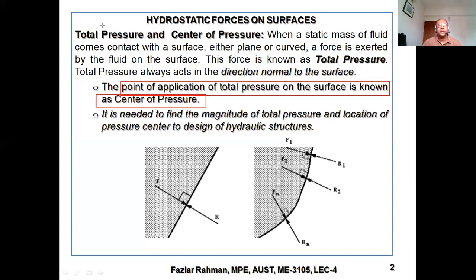Right over here, you see a curved surface in contact with a fluid. So what will happen? The fluid pressure at every point will be perpendicular to the surface. And gradually as you move upward, the pressure will decrease. At the top surface, it will be 0. Now how will this resultant be balanced? By the strength of the wall. So your reaction force will work along this direction. That means the wall will resist all the force.